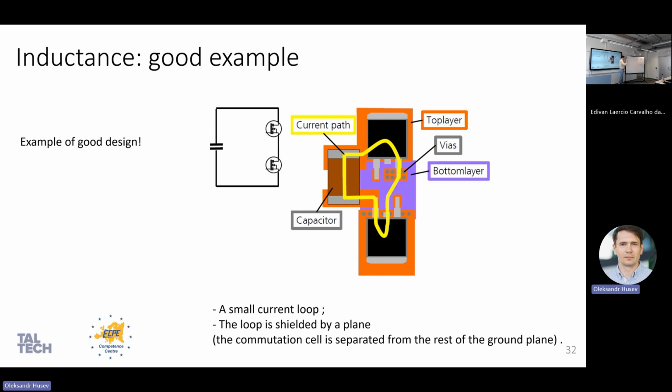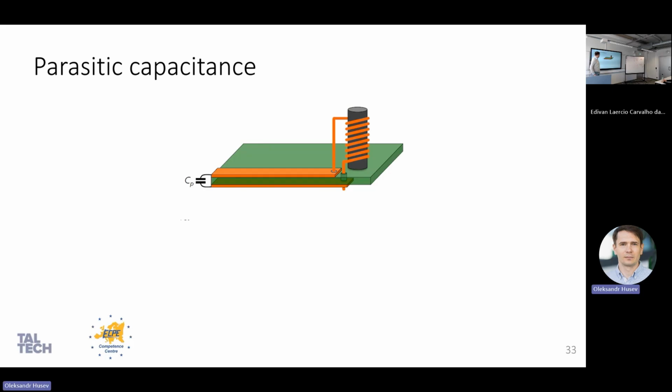Despite that, you may think, oh, but it's a shorter distance, so lower inductance. No, inductance, by definition, is how much magnetic flux you create. And by this connection, you create lower magnetic flux. Clear? But there is bad news. What about capacitance?